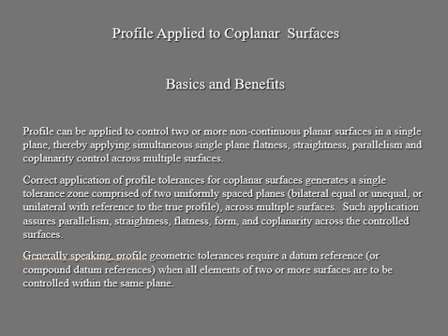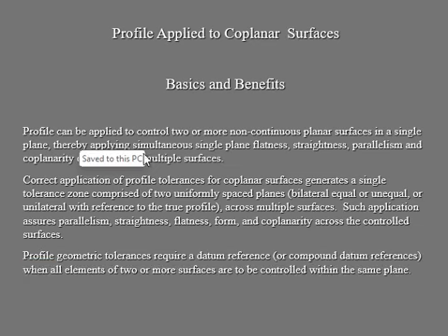Your benefits, of course, profile can be applied. You can apply the profile to control two or more non-continuous planar surfaces in a single plane. That's why we call them coplanar surfaces. And you can do it simultaneously: single plane flatness, straightness, parallelism. They all control these multiple surfaces, because for parallel you need two surfaces. Straightness, we also look at it.